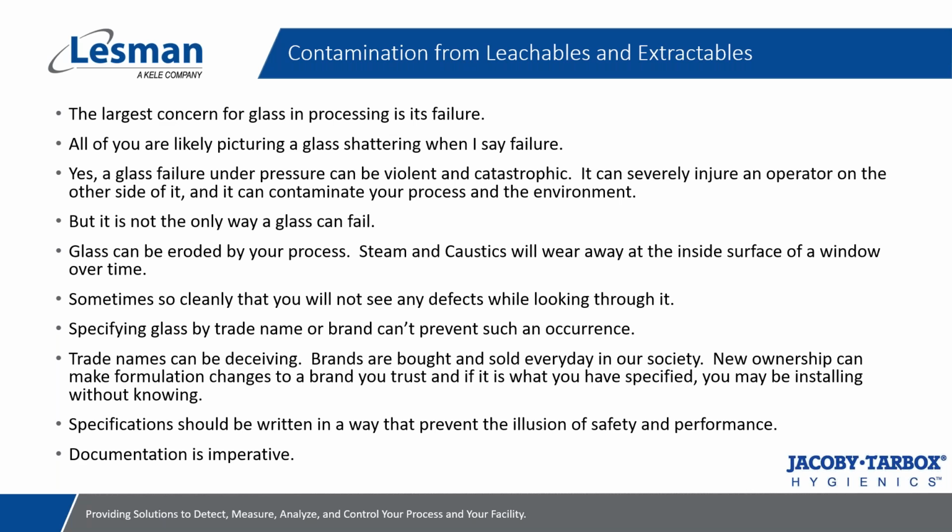And glass shattering is violent, it's catastrophic, and it can certainly severely injure the operator on the other side of it, and it will contaminate either your process or the environment or both. So when we think about a radical failure, a catastrophic failure, glass breaks at about 5 miles a second under pressure. And that is as violent as it can possibly be for a piece of equipment that somebody will have their face on the other side of multiple times a day. So we try to make our windows, our process observation equipment, as safe as possible.